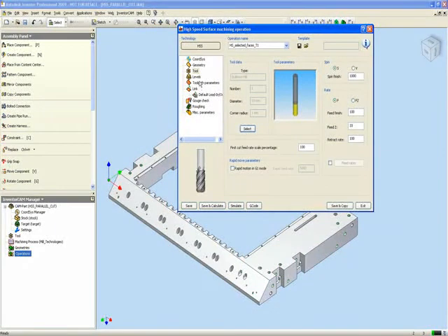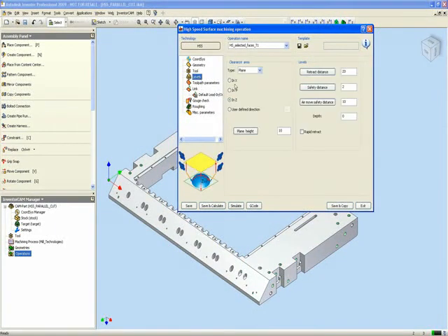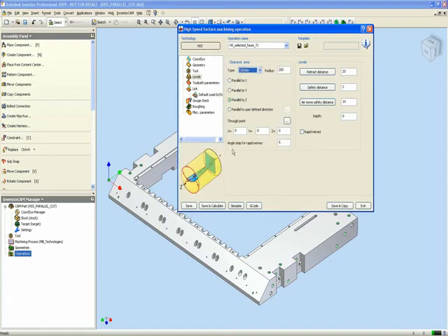Next, I'd like to go into levels. Now, in levels, we have the choice of having a clearance area going up to the top plane, as shown here, or if we're working on a cylinder, actually have it going to a specific cylinder around the part if you were working on a machine with an indexial fourth axis.